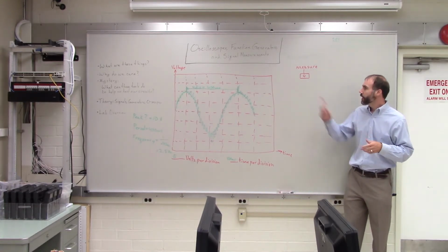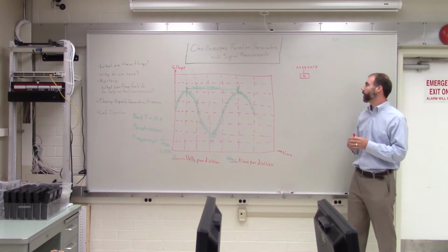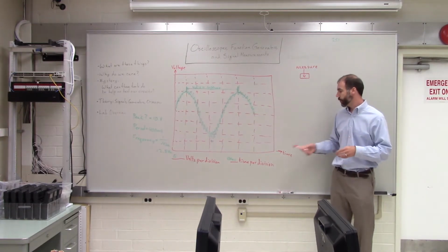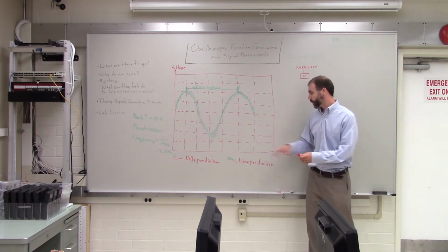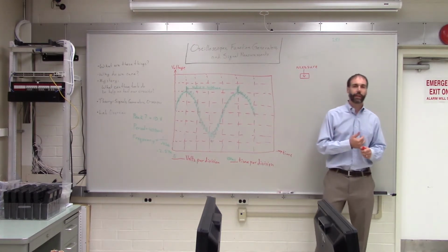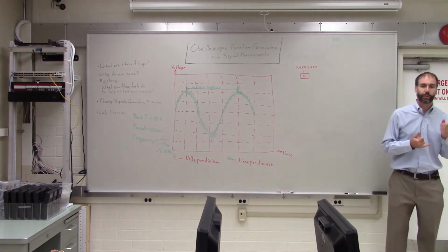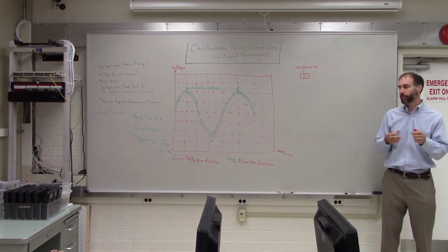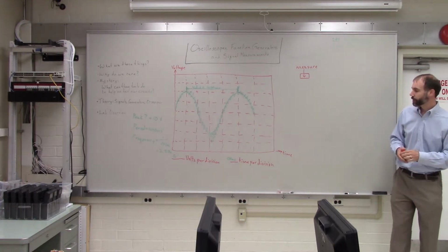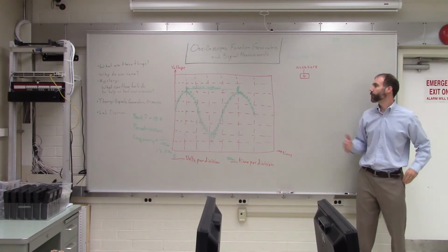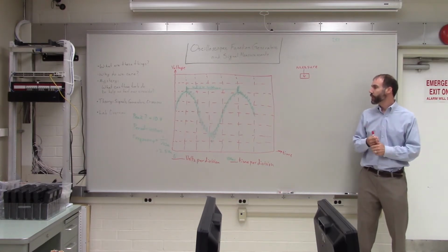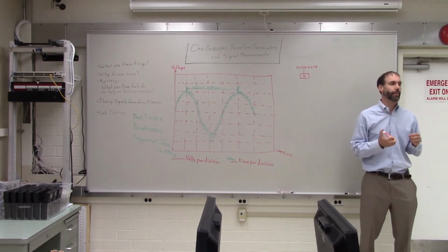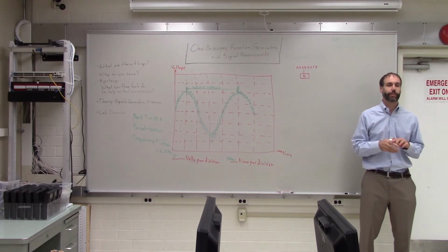Okay. Back to the oscilloscope. The measure button on the top allows you to measure all those different things, and it just creates small readouts down at the bottom of your screen that have those measurements listed. So you can see the peak-to-peak amplitude and the frequency and the duty cycle, or the time high, all displayed at once if you want. You can choose whichever ones you want. So that's one thing. If you have a nice clean signal, the measure function is the easiest way and the quickest way to get those measurements. Okay?